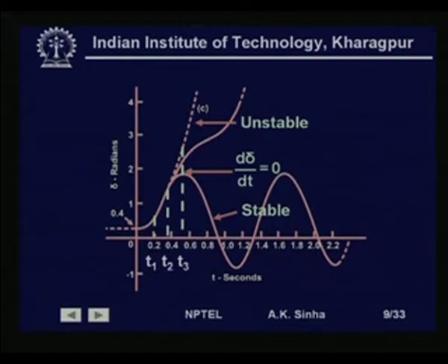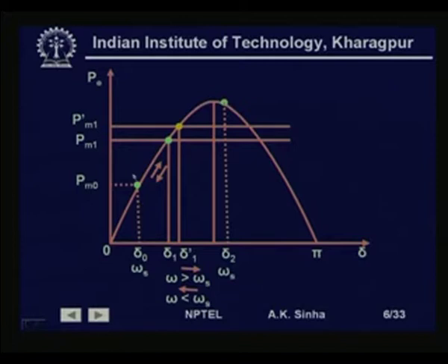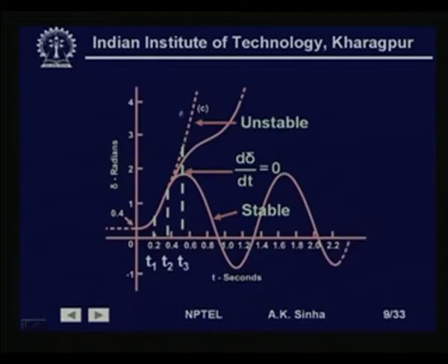Okay, as we have seen, when we make these assumptions and work with the change from PM0 to PM1, what we will find is an oscillation or a delta angle change which will look like this. Here I have modeled small damping, that is, if you see, the oscillations are dying out a little. So, this is what will happen, we will have delta angle oscillations as we had seen earlier. This delta versus time plot will look like this.